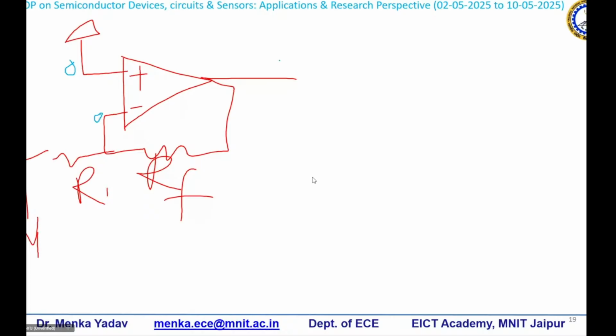What will be the output voltage VO? From this we found it. How did we find it? We applied KVL. We are presuming that this op-amp is the ideal op-amp. If it is ideal, there is no current flowing into it, because the Ri seen over here has an infinite value. Ri is equal to infinity. So there is no current through this, which means there is no IR drop across it, and effectively here you have 0.